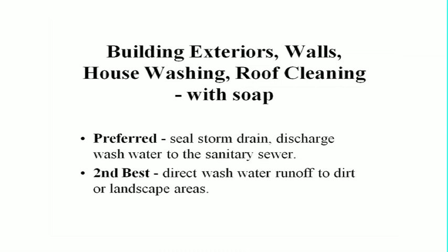Now, you always want to pre-clean and you always want to filter. That means through an oil absorbent boom and a screen. A lot of times you're not going to be able to discharge wastewater with chemicals. If you're using chlorine or bleach, that needs to be neutralized and discharged to landscaping.